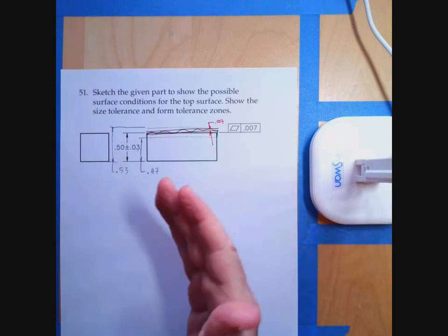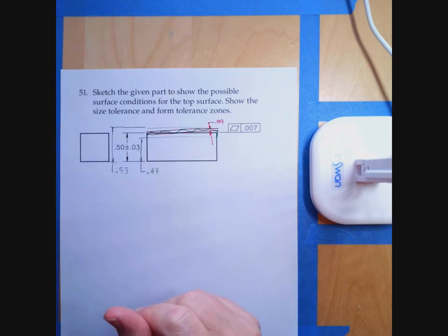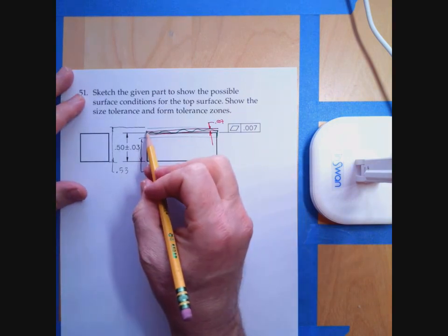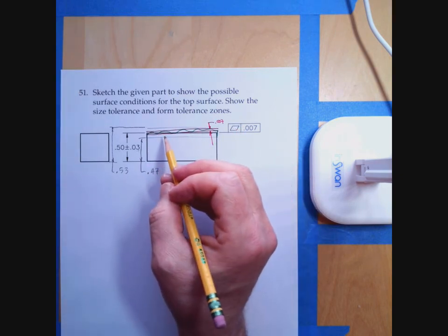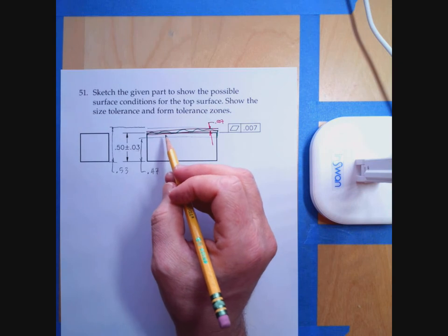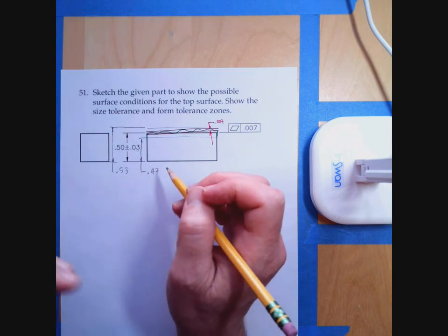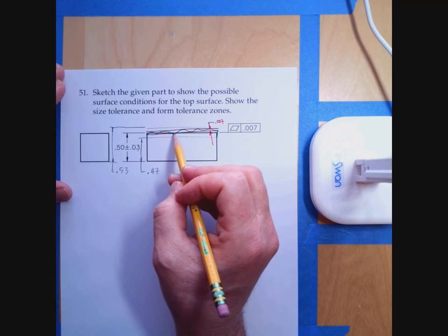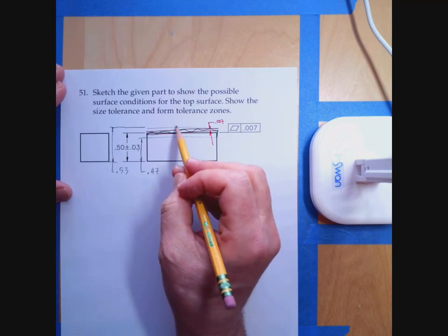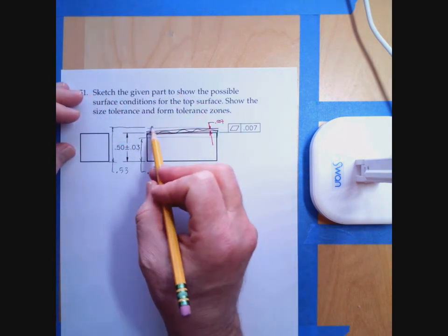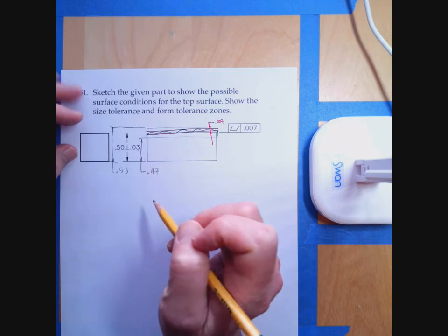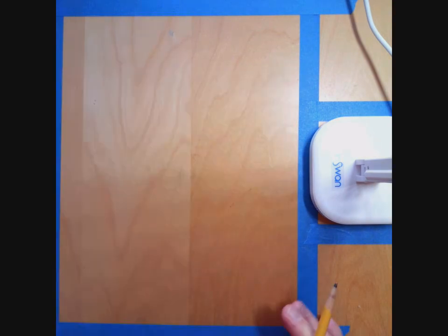Now, of course, there's a lot of other answers that are equally valid. That's just one of them. I want you to note, though, remember, the flatness tolerance, and in fact any of the form tolerances, straightness, flatness, circularity, cylindricity, are not oriented towards any feature. That is to say, they don't have to be parallel to the bottom surface or parallel to these two. So it's free to float at an angle, provided it doesn't go above or below the max and min sizes.